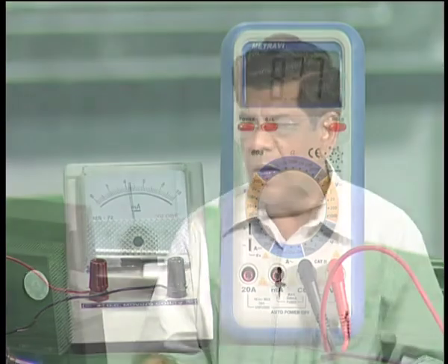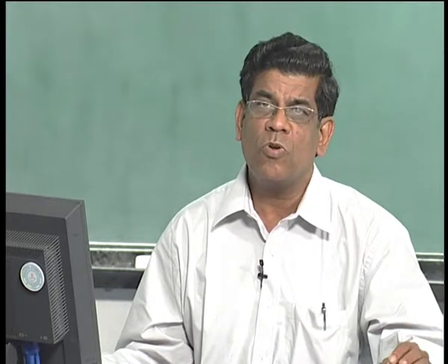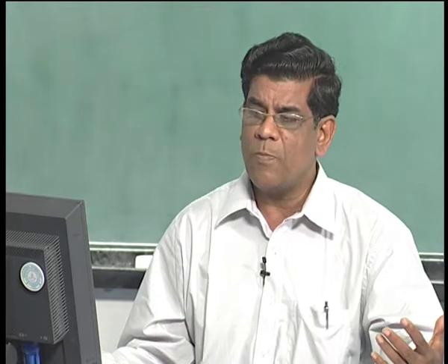So, we saw the characteristics of the junction field effect transistor, how for different gate source voltages the saturation current comes differently. If I increase the gate source voltage to minus 1, minus 2, the saturation current comes to lower values. You have seen that. But one of the greatest advantages of the junction field effect transistor that I already mentioned to you is the capability to make the junction field effect transistor on the same side of the silicon wafer.